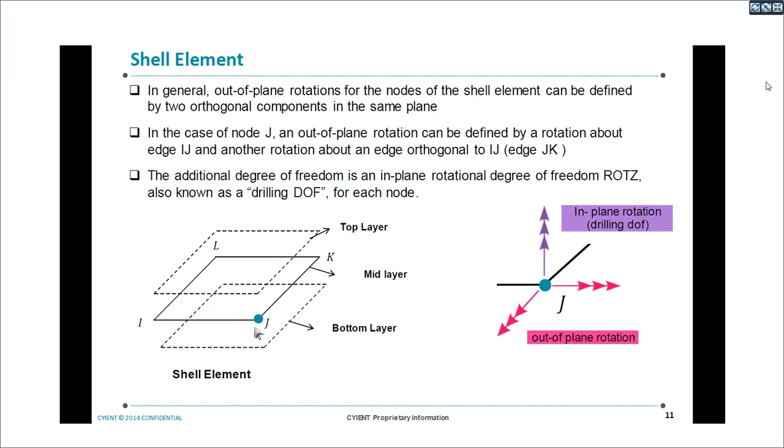So when a component is subjected to a bending load, it will be like this. Here the program will calculate at the mid surface, but it has to interpolate at the top and bottom. So how will it interpolate?